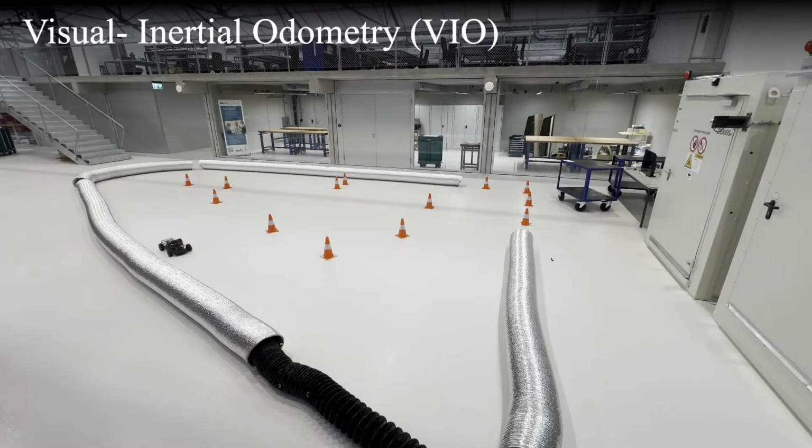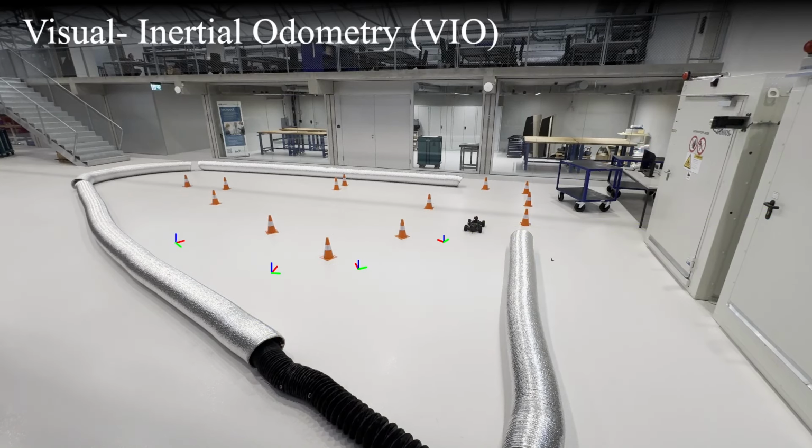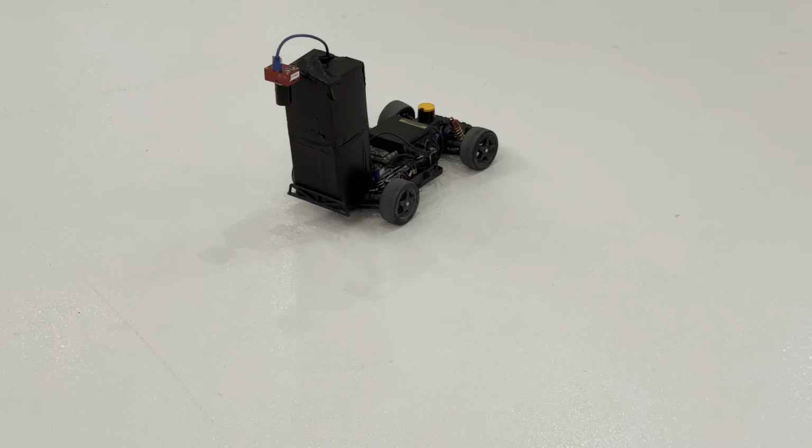A common approach, especially in the UAV domain, is to use cameras and do what is called visual inertial odometry. Hereby, landmarks are detected in the camera, which are then triangulated to determine the vehicle's pose. When this is done continuously, one can construct a graph of the vehicle's poses, and by taking into consideration the measurements of the inertial sensor, one can estimate the vehicle's velocity in 3 dimensions. However, most wheeled robots, especially autonomous cars, only move in 2 dimensions.